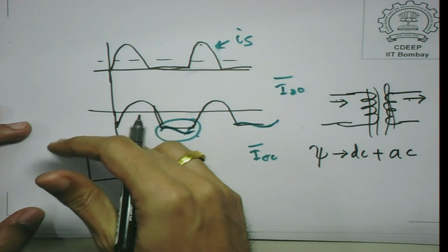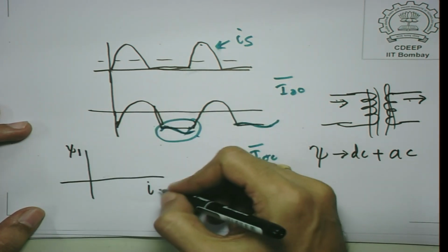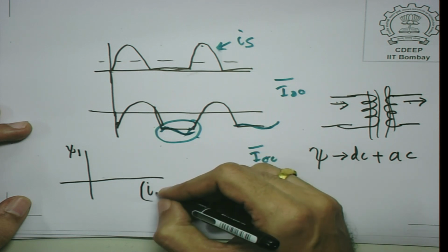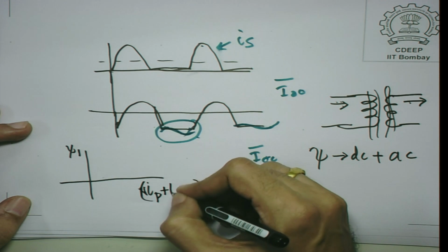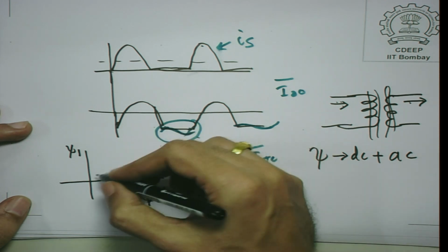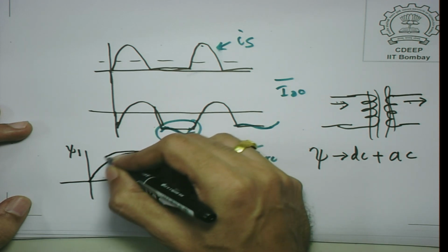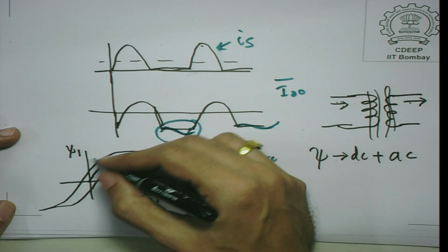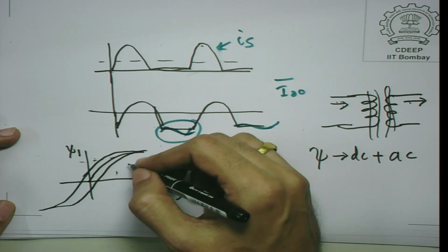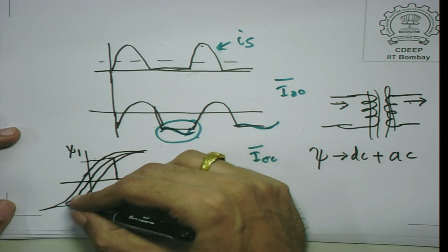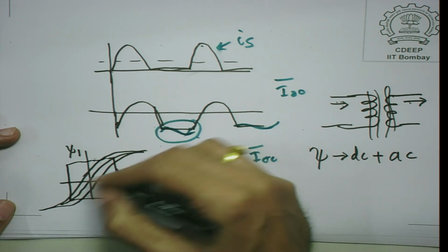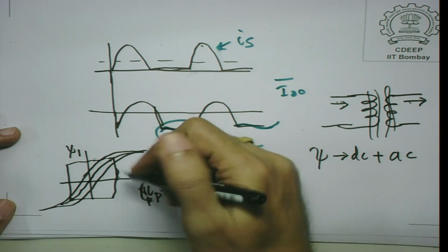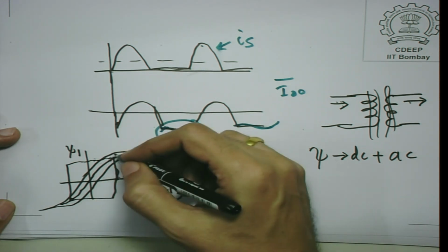Now, what happens because of this, if you take the flux linked versus current relationship, say this is the flux linked with the primary winding and this is the total current, that is the MMF in fact, N primary plus N secondary. You will find that since the core is nonlinear, the flux and the current are linear up to a certain point. There is a hysteresis also, I have slightly exaggerated the hysteresis. So, normally you are working in almost the linear region. If you are AC, you will traverse both positive and negative, you will go in this quadrant and this quadrant. For cores of this kind the hysteresis is usually small.